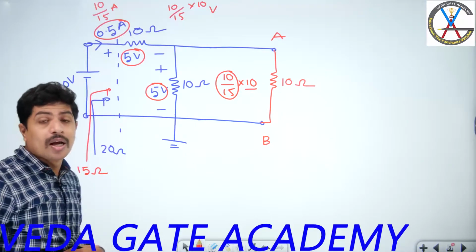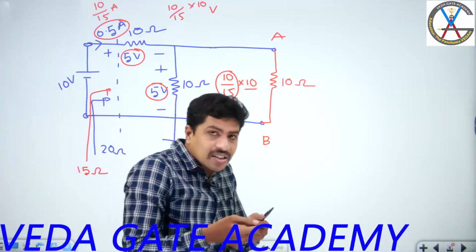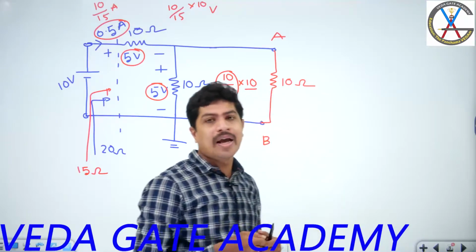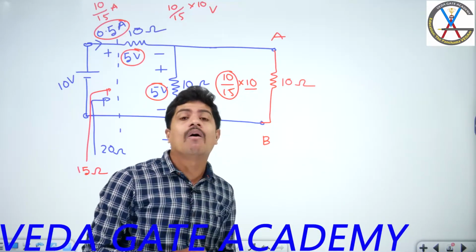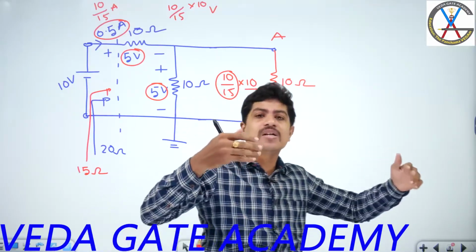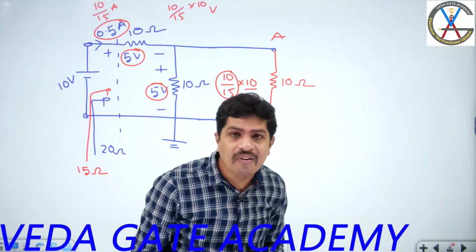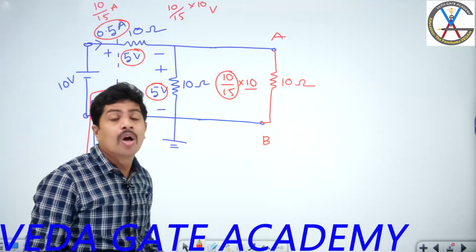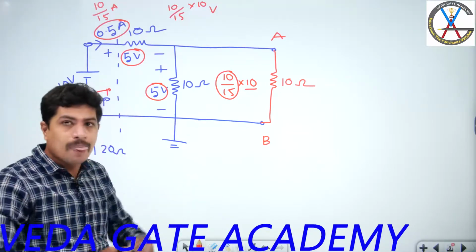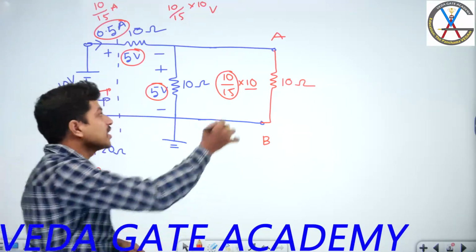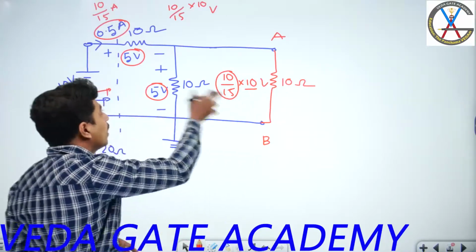That is the voltage. It means as and when you connect a new element into a circuit, all the previous voltages and currents will change. This effect is called the loading effect. This effect is called what? Loading effect, or vice versa. Now imagine the first case is this 10, 10 and 10.